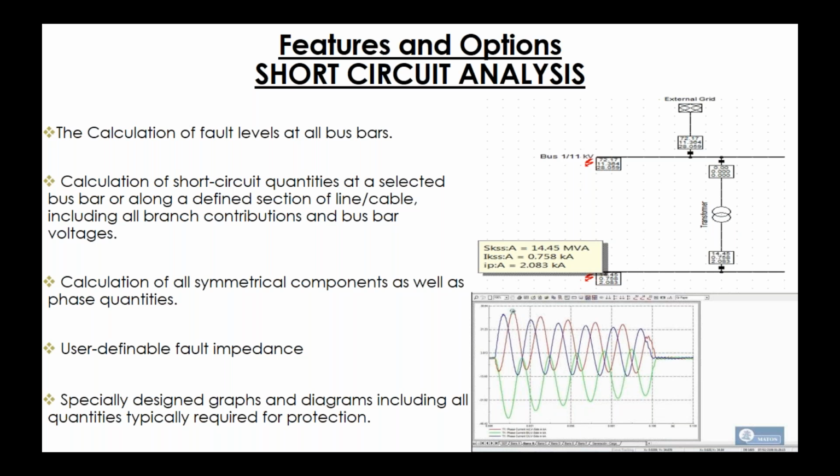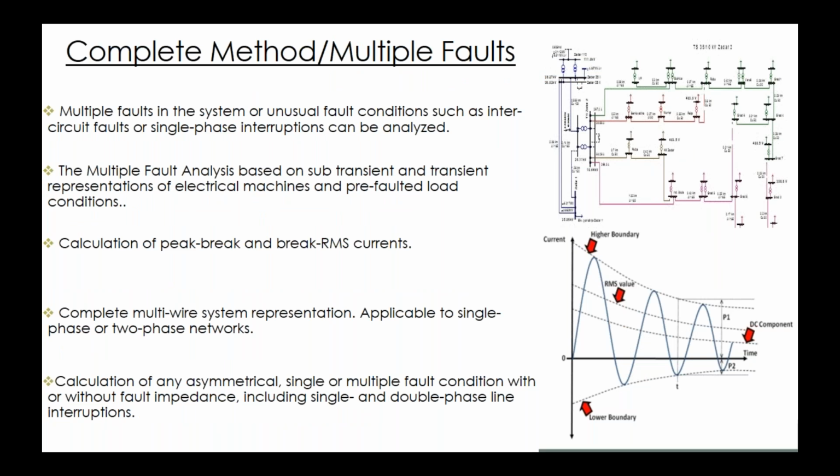Typical examples of short circuit analysis in system planning include ensuring the defined short circuit capacity of equipment is not exceeded with system expansion and system strengthening, coordination of protective equipment, fuses, overcurrent and distance relays, dimensioning of earth grounding systems, verification of sufficient fault levels and capacities at load points, and uneven loads such as furnaces, thyristor drives and variable speed drives, or dispersed generation.